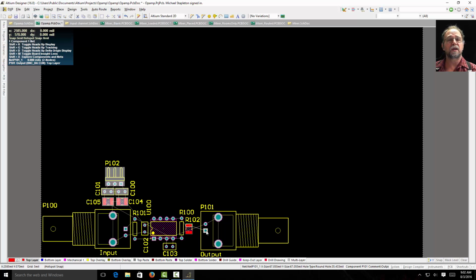But look, I have a giant board and all my parts in the bottom left. How do I change that? How can I change the shape of my board? Well, let's change it because it's very, very easy. Under the bottom here, you'll see I have tabs. Top layer, bottom layer, top overlay. That top overlay you see is yellow, just like the box. The top overlay is the silk screen. I want to click on this one that says keep out layer. The keep out layer is what we're going to use to define the board shape.